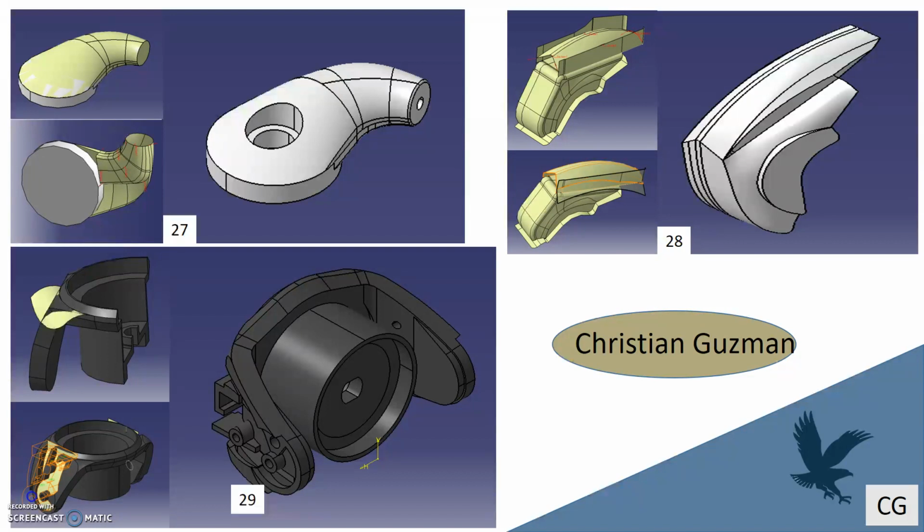The picture on the right is the rear cover. It starts from extracted surfaces of some other parts, and then uses multi-section surfaces and goes through trim tools. I generate the complete surfaces of the rear cover, and then also create closed surfaces in order to give a volume to the part.